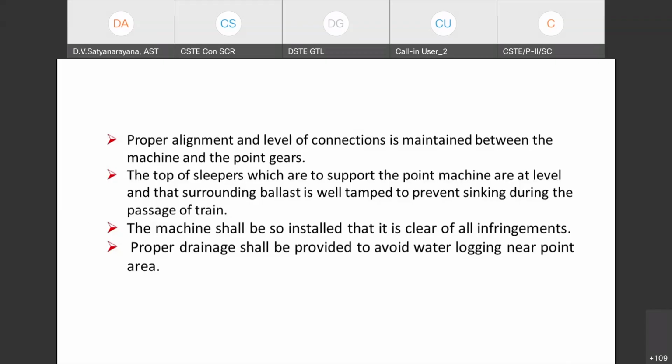So, Murli, now you have been in construction for 6-7 years. Prior to that, you were in open line. So, when the points are being assembled by the engineering department, before we fix the point machine, what are the items that you are checking before you take over the point layout from the engineering department? The point should be at correct levels, sir, so that we can move both tongue rails easily, and the tongue rails will flex freely on both sides, sir. That should be ensured. How many sleepers? Housing 1 to 6, the first 6 sleepers, sir.